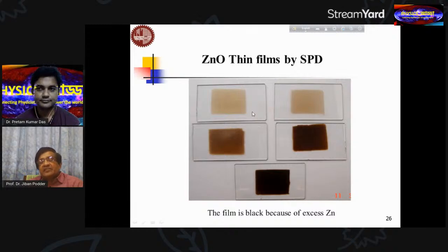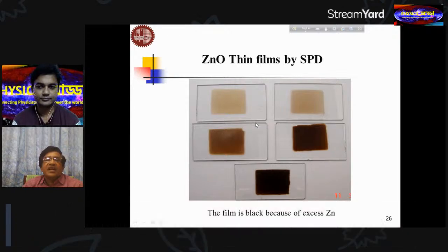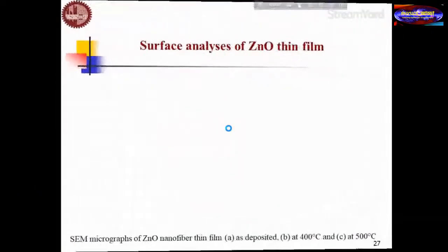Normally, in the spray pyrolysis technique, we use a molar concentration of 0.1 molar. This is almost a standard. So we prepared a 0.1 molar concentration of the precursor solution, and we maintained the temperature on the hot plate, that is the substrate temperature, at around 300 to 500. That temperature is required to decompose all the salts to form the solid structures and solid material, as a coated material in the form of thin films. So these are the things we did.